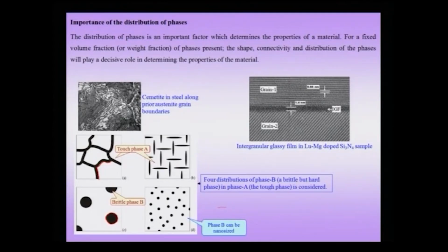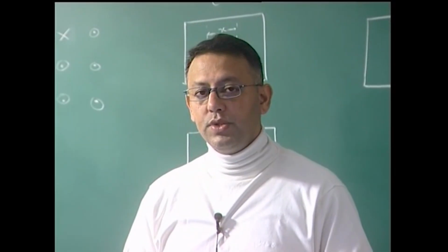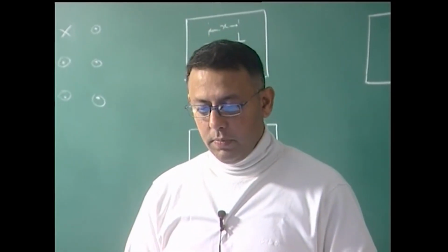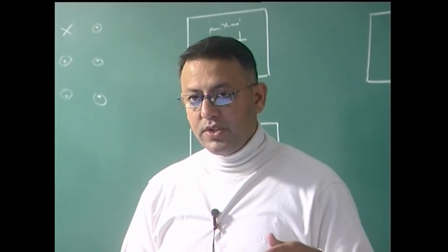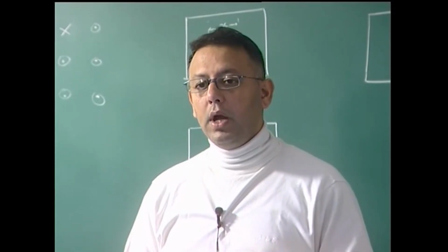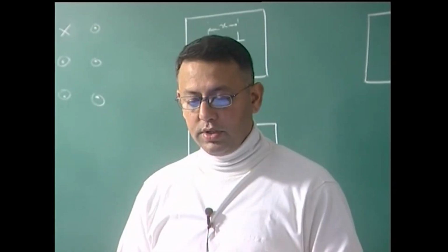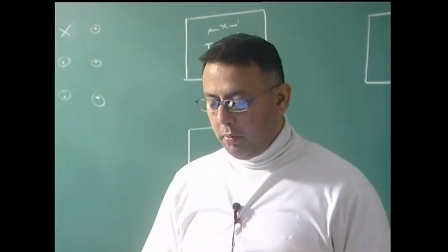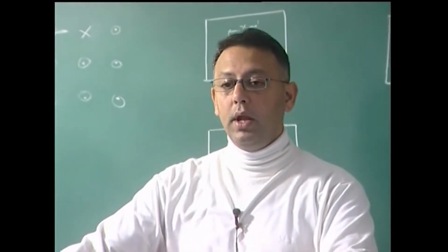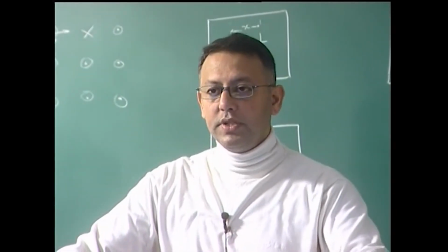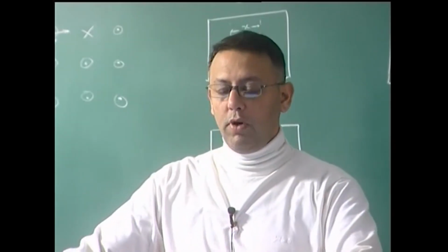So, this is my interface boundary. Now, as I had pointed out when we were discussing this aspect, the interface properties are very, very important with regard to the material as a whole. In other words, if we have interfacial debonding or any one of those phenomena, or nucleation of cracks at the interface, then the material as a whole would actually perform poorly.